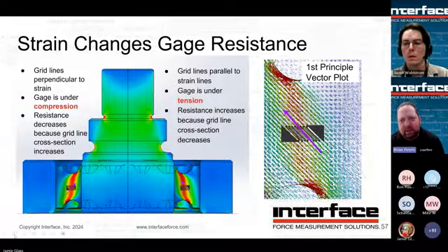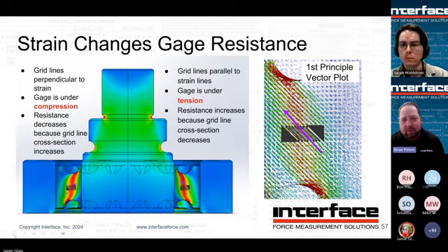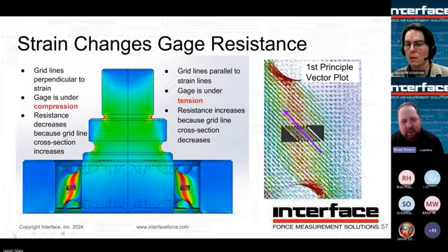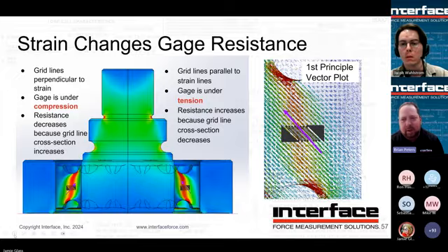So not only is the low profile design radially symmetric, which lends itself well for handling any non-axial load, we use 8 strain gauges, and then we do another step further called moment compensation, which we'll touch on. But I just want to highlight that. So through the design of the flexure, through the placement of the gauges and the types of gauges used, we can make these sensors very robust to reject anything other than measuring the actual axial force that's popping up.